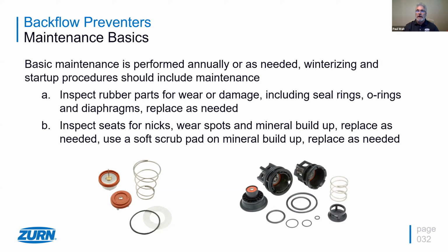And also, you have to think about it from a perspective of, hey, I've got all these test cocks, all 4 of them are quarter-turn ball valves. So a lot of people forget to do the 45 on the test cocks, and you end up losing a couple every year. And then once you learn that process, just go through and winterize those test cocks the same way. Okay. Yeah, good question there.